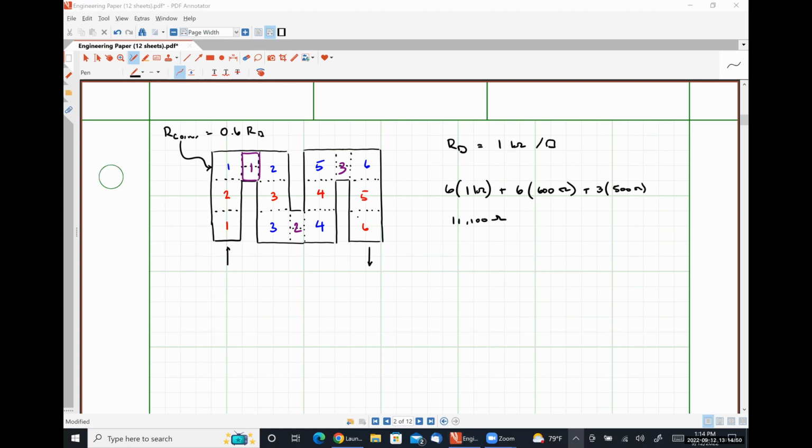So if we had knocked that guy off right there, we would have something pretty close to a 10 kilo ohm resistor, but it wouldn't be nearly as long. It just takes up a little bit of area. So in analog circuit design, where resistor values are much more important, corners actually largely get avoided.